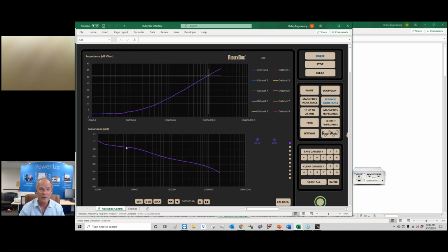Giving me one value of leakage. I mean, where would you put the one value? Put it there, put it there, put it there. It's a 2-to-1 range. Gives me no quality control over this transformer whatsoever.